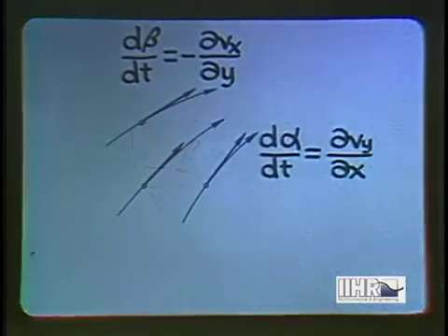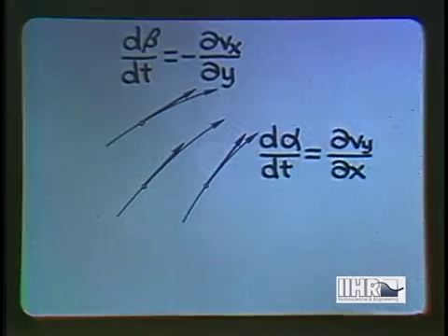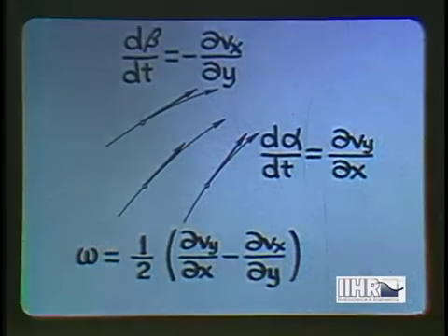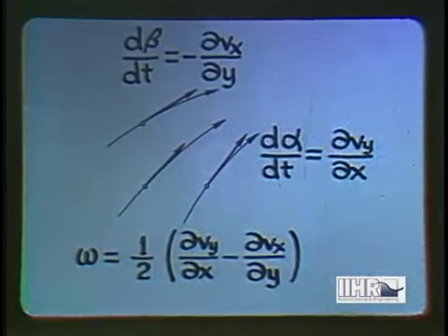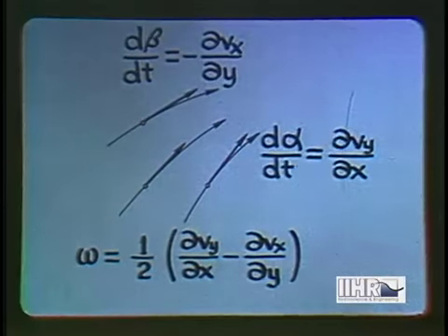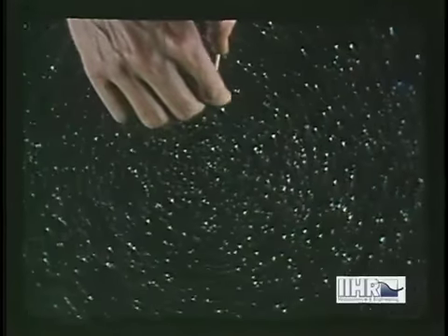The net vorticity in a given plane depends upon the average of the velocity gradients in the two normal directions. This in turn would be indicated by the average tendency of two lines or sticks at right angles to each other to rotate. In the case of water in a tank rotating about its axis, the velocity varies directly with the radius. Obviously, lines or sticks either tangential or normal to the streamlines will rotate just as they would in the vortex filaments seen before.